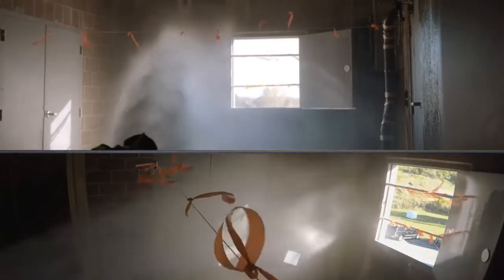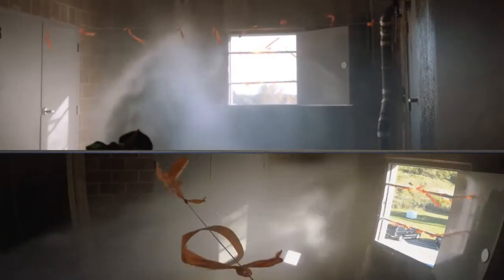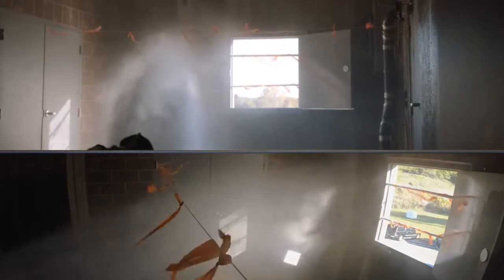Consider that this fog stream is pushing around 10,000 cubic feet of air per minute. We used to say if you pointed that fog stream toward an opening, the fog would drive all the products of combustion out. As evidenced here, we know that's not true.